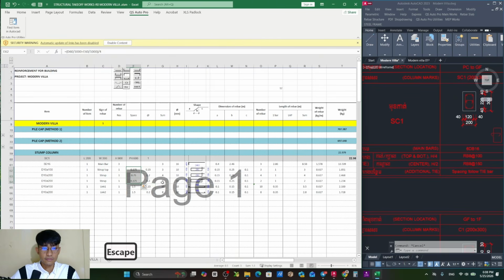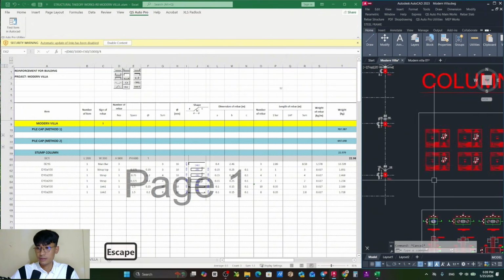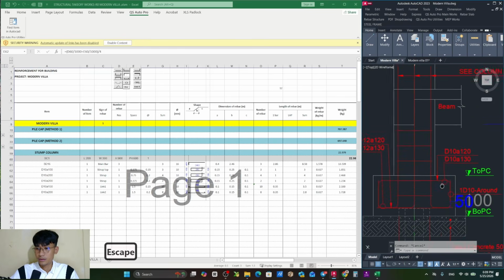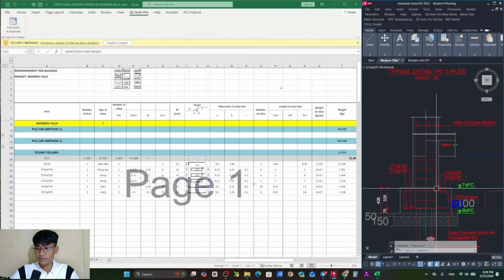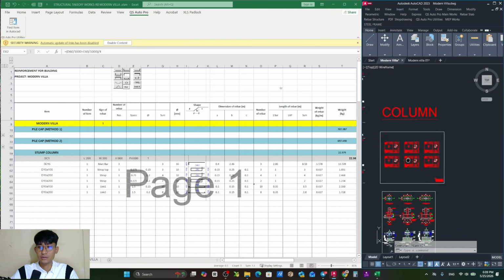So the total is 1.5, and the total here is 1.5 as well, as you can see. So the height is correct. Okay, so we have the height from here to here, and for the stirrup itself, from here it is the height divided by 4, the height divided by 4, and at the middle it is divided by 2. Okay, you can take the full height as the same, but it's up to you. But based on the detail, we have to take it, you know.